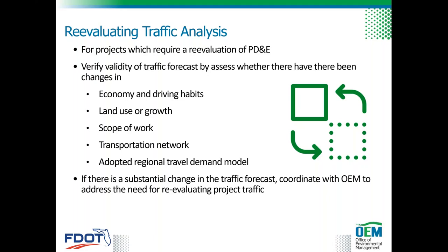Another consideration is the adoption of a new regional travel demand model when the project traffic is more than 5 years old. If the traffic forecast is more than 5 years old and the MPO has adopted a new LRTP, then the project manager and the traffic analyst should perform a sensitivity analysis of revised input and model assumptions to determine the magnitude of differences from prior analysis, and therefore determine the effects on past project decisions.